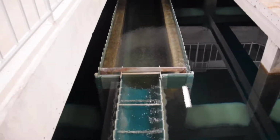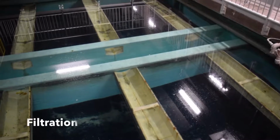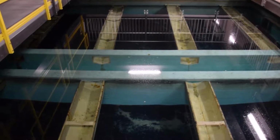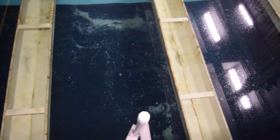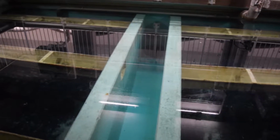This plant has 12 dual media gravity filters, which have a total filtering capacity of 145 megaliters per day. Water above the filter media forces water downward through the filter, and suspended matter such as silt, clay, algae, and pin floc are removed by the media.